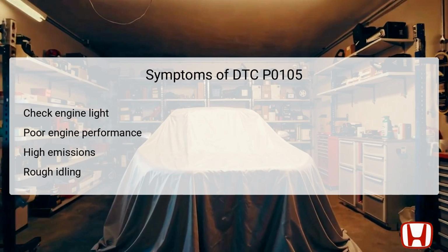These symptoms often result from inaccurate MAP sensor readings, leading to poor engine performance. Additionally, increased emissions might occur as the ECM struggles to adjust the mixture for optimal combustion. Understanding these symptoms can guide technicians in identifying and rectifying the underlying problem effectively.